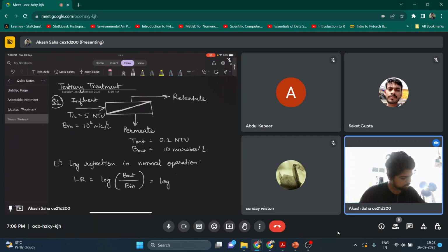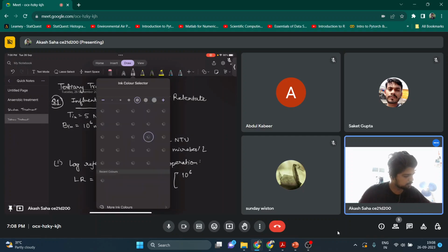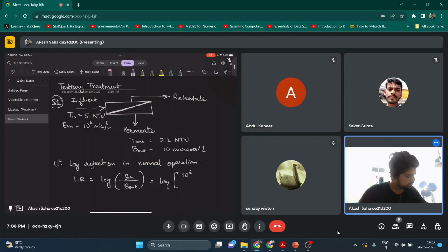Oh, sorry, it will be log of B in by B out: 10 to the power 6 organisms per liter divided by 10 organisms per liter. So my log rejection is 5.